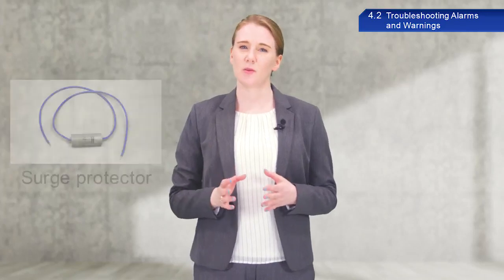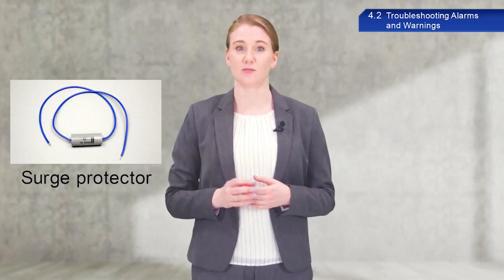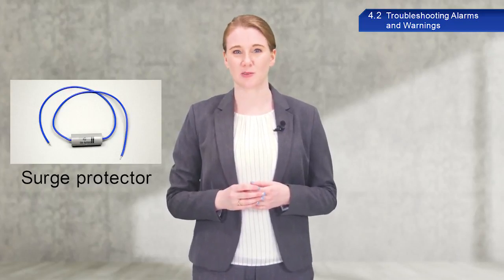The most common noise problem is due to the bundling of servo amplifier input and output wires with signal wires. Try running these wires separate from each other. If equipment near the servo amplifier generates significant noise, try installing a surge protector for this equipment to reduce the noise generated.